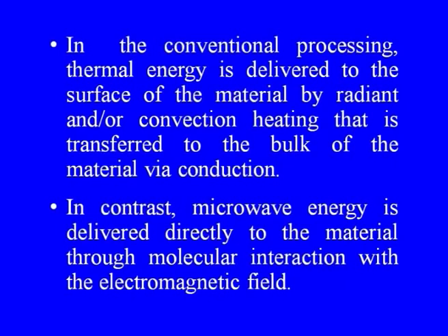In conventional processing, thermal energy is delivered to the surface of the material by radiant and or convection heating, and is transferred to the bulk of the material via conduction. In contrast, microwave energy is delivered directly to the material through molecular interaction with the electromagnetic field.